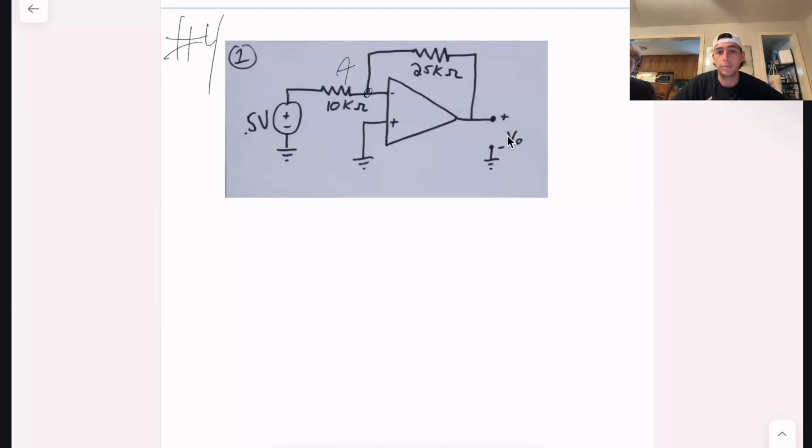This is an operational amplifier, and what they do is they can increase a voltage from the beginning to the end of a signal. There are also some characteristics of an operational amplifier that you need to know for this class. We're going to assume every op amp in Circuits 1 is ideal. Later on, that's not true, but for this class, you always have an infinite open loop gain, which essentially means that the maximum gain of the op amp isn't limited by any internal factor. It's always going to be based on the resistive network around it.